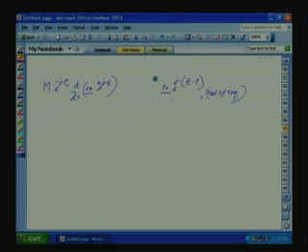See here, this IR is originally defined with respect to the rotor axis; when multiplying by e raised to j epsilon, it will come to the stator axis. Then again multiplying by e raised to minus j rho, it will go to the dq axis. So, the result will be IRd plus j IRq.